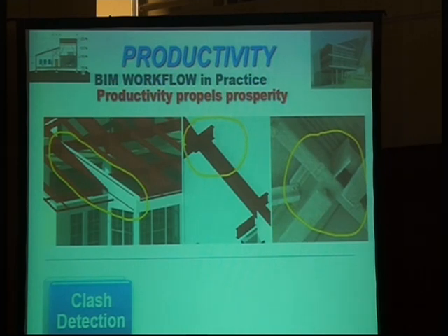In this one, it shows you how it will be, to see the benefit of BIM when we do the coordination. So in this example, you see once we link the model together, we saw there is a collision, there is interference between the trusses, the steel truss, and the curtain wall, aluminum curtain wall. So they are colliding. Open. Problem. So that must be resolved. And once resolved, the photo on the right shows the correction after being constructed and resolved.